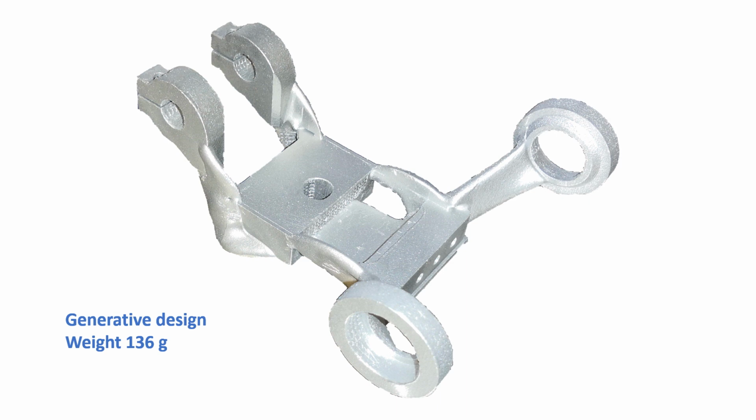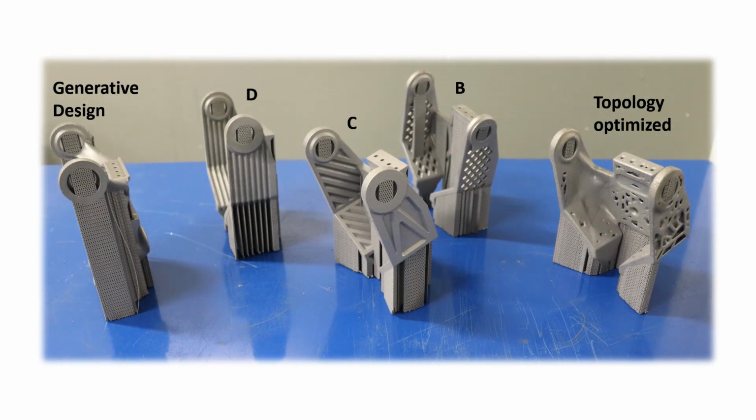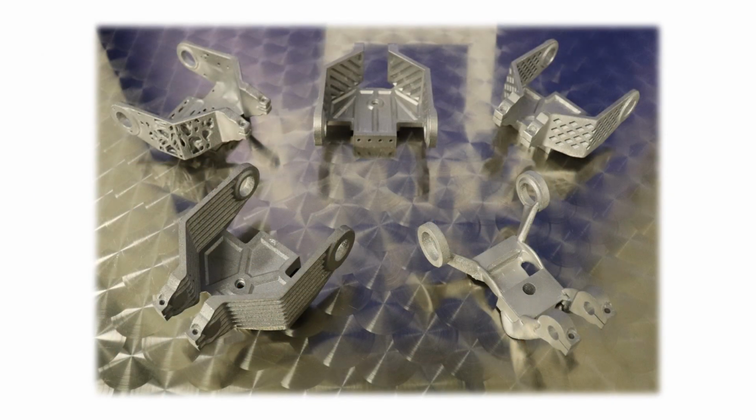Generative Design software works by defining joint geometries, loads and areas where the material must not be in the part, and based on this the software calculates several alternative structures that implement boundary conditions. The picture shows all the pieces of the support structures. The design of Part D has best taken into account the support structures, and their removal. There are a lot of support structures in the generative design section.